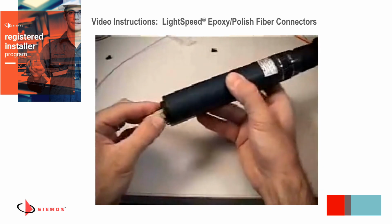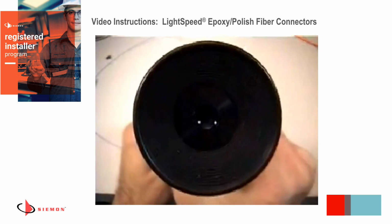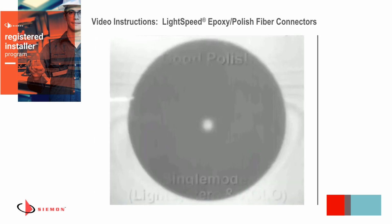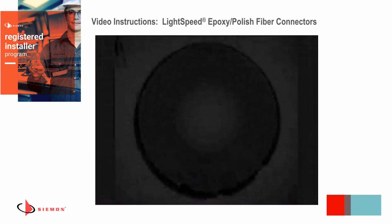Fully insert the ferrule into the microscope, depress the button to illuminate the end face, and inspect the fiber to ensure there are no scratches, voids, or chips. If the polish is acceptable, place the dust cap on the connector until your network connection is ready to be established.